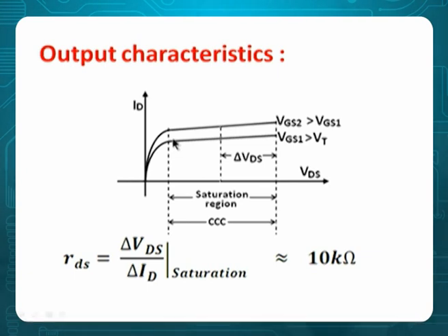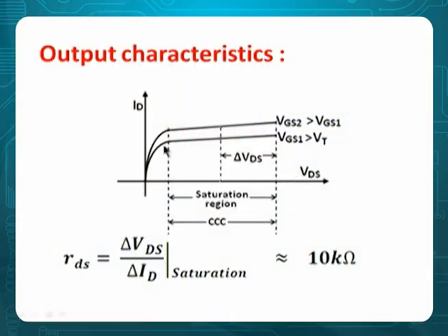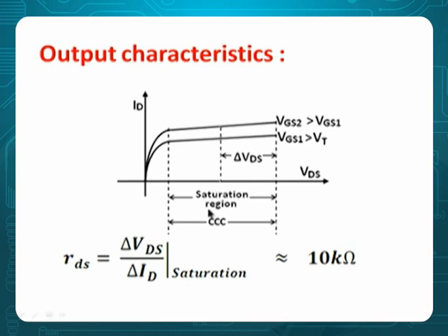When the carriers are increasing, we normally think current will increase, but because of collisions, the current does not increase. When VDS is increasing, current is increasing, but the carriers get collided. When they collide, you know what happens? There is no movement or restricted movement. That's called the velocity of the carrier is saturated. When the velocity of the carrier is saturated, it is called the saturation region.